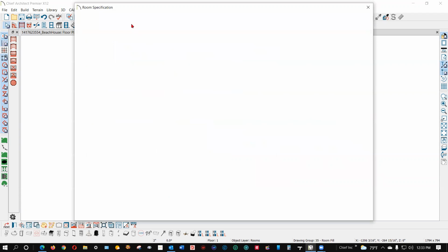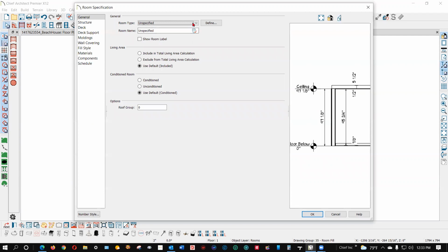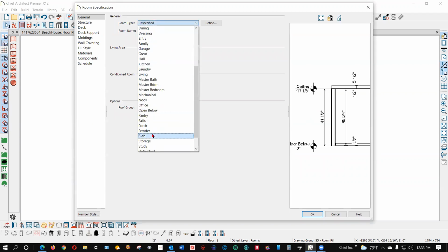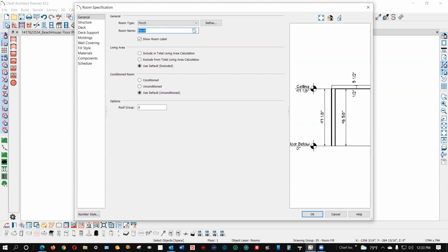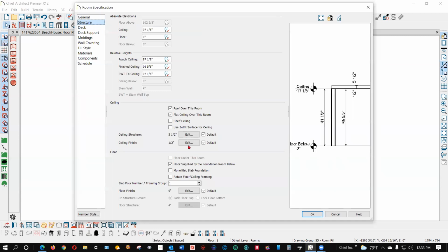So I'm going to open this new space that I've enclosed with railing walls. And we'll give it a name. I'm going to call it porch, and display it be portico. And porch will go with a concrete floor. And I'm going to lower the floor 6 inches so it's lower than the house, closer to the ground, so you don't have to drive a ramp up to get a car on it.